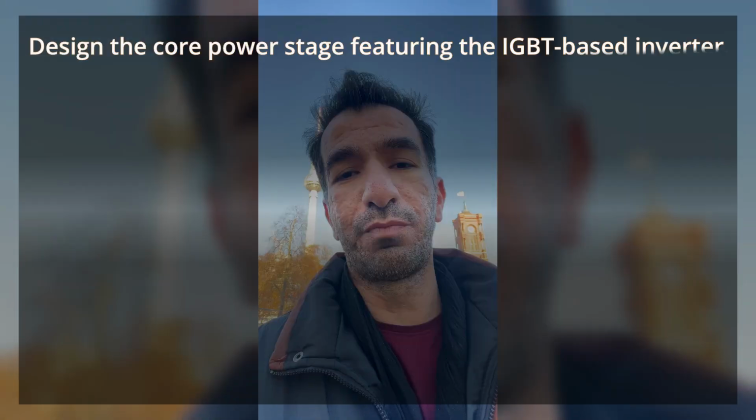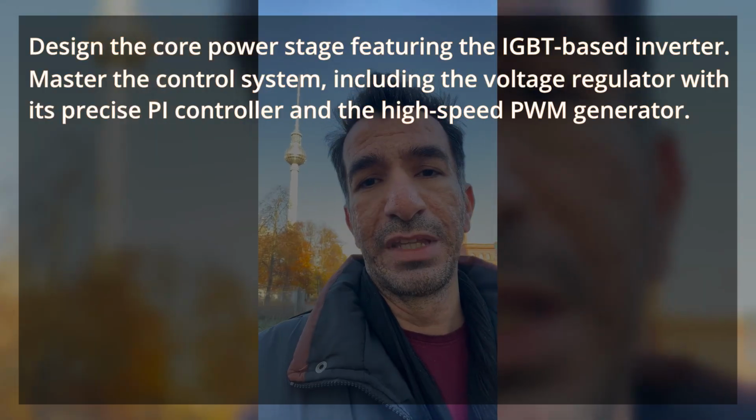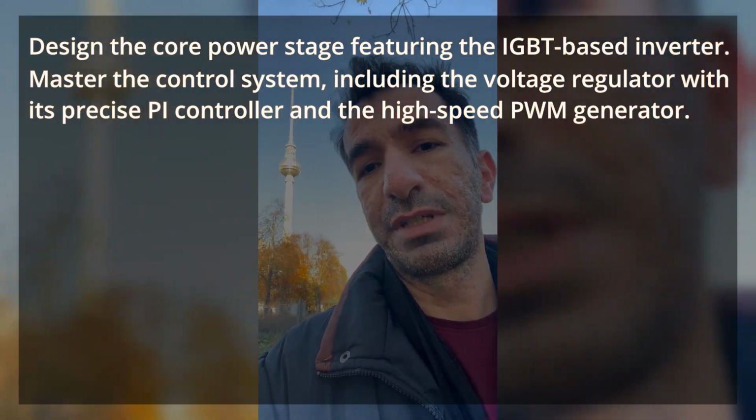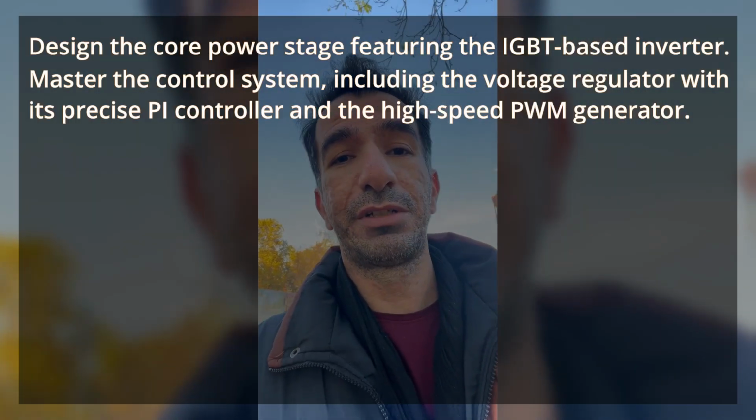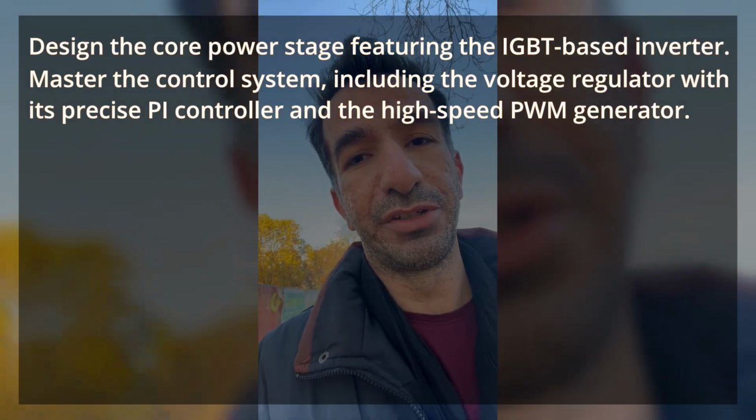Here we are opening up the complete Simulink model for a three-phase on-grid inverter, breaking it down piece by piece. I will show you exactly how to model the critical hardware and implement the control logic. You are going to discover how to design the core power stage featuring the IGBT-based inverter and master the control system, including the voltage regulator with its precise PI controller and the PWM generator.